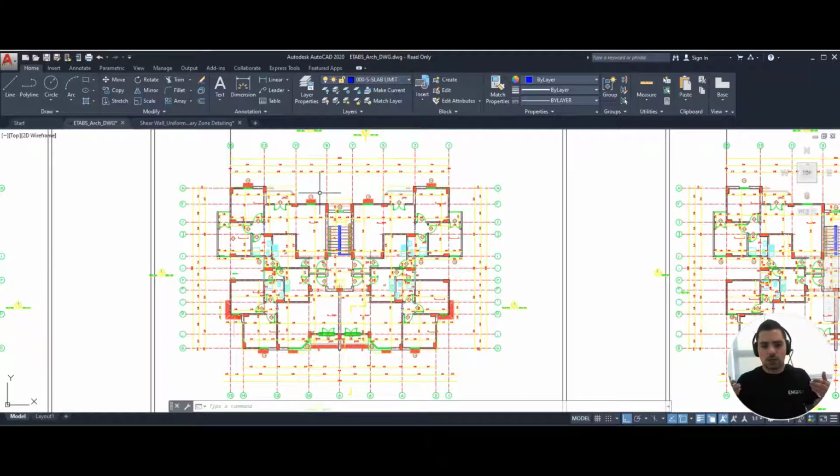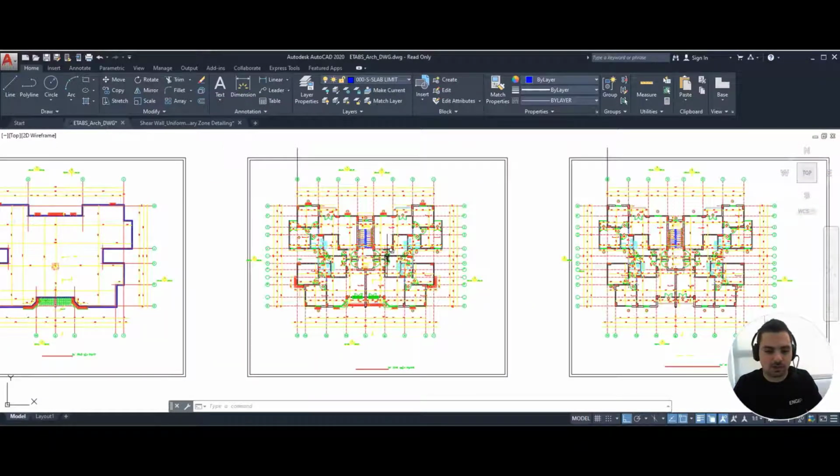So if we want to take an example of that, usually if you want to rotate an object, you do not rotate an object from the center. You hold it from the edges and you rotate it. Now this is the same case here. The bigger the lever arm, the better the resisting force is, or the better the resistance is against earthquake loads or lateral loads in general. So this is the reason that we place our shear walls along the outer periphery of our system.